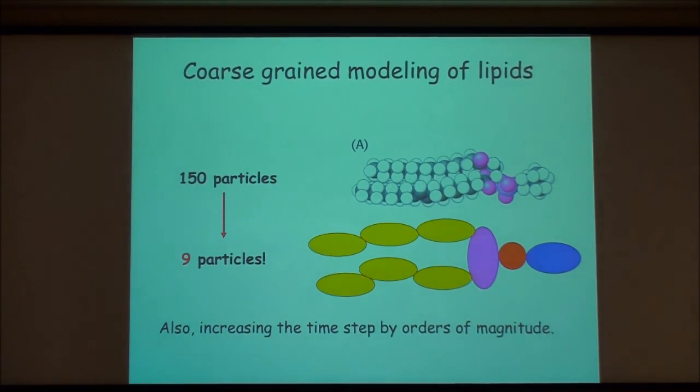Are you with me? Usually when you have explicit, atomistic water in your simulations, the dielectric effect should come from those explicit water molecules. They fluctuate, they polarize in response to the environment, so they will give you explicitly the dielectric effect. When you do coarse-grained water, you will not have the dielectric property because it doesn't have a dipole moment. Therefore, you have to implicitly include that dielectric effect. There is a command in the NAMD configuration. You turn on the dielectric constant, and you specify what dielectric constant you want to use, 80 in this case, or 78. And that affects all Coulomb interactions that are calculated in your forces and energies. Everything will be scaled by 80, essentially.